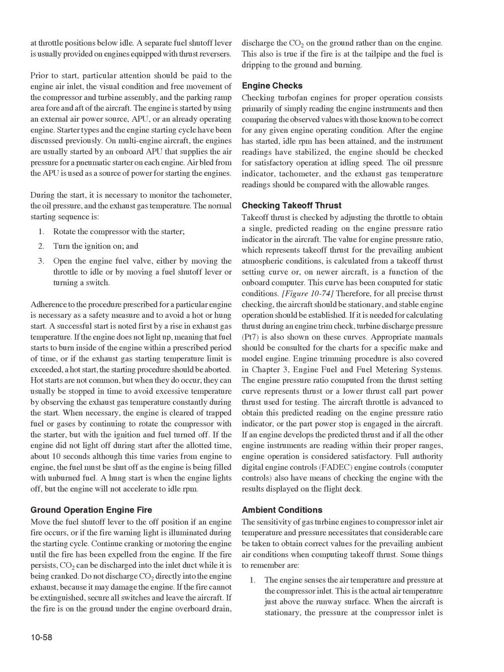When necessary, the engine is cleared of trapped fuel or gases by continuing to rotate the compressor with the starter, but with the ignition and fuel turned off. If the engine did not light off during start after the allotted time, about 10 seconds, although this time varies from engine to engine, the fuel must be shut off as the engine is being filled with unburned fuel.